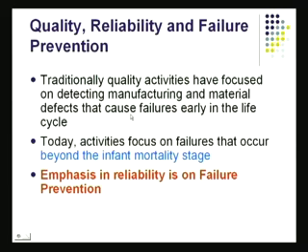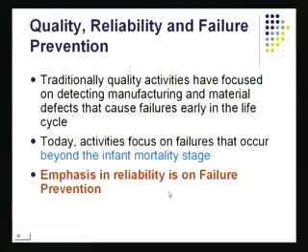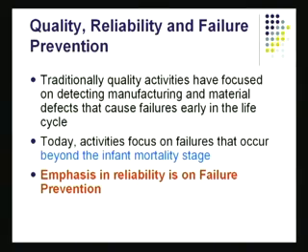The job of reliability engineering is to try to prevent failures, to do whatever you can to reduce failures. This is the mission. And this is to be done beyond the infant mortality stage. We understand that infant mortality is because of manufacturing defects, as you are getting products straight off the line. Not many products will have these problems, perhaps just a few percent. But it's the period of use over which I've got to make sure that failures are rather few and next to zero if possible.